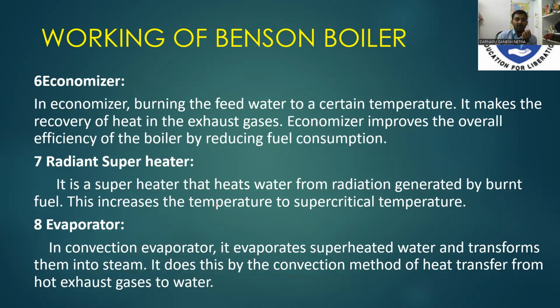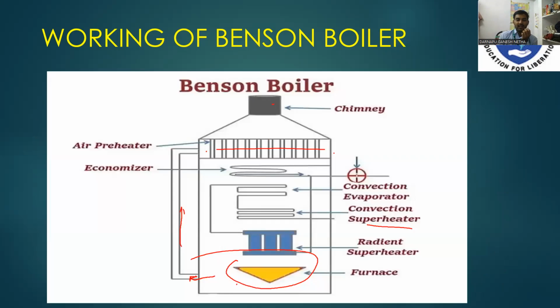Economizer. An economizer heats the feed water to a certain temperature, making use of the recovery of heat in the exhaust gases. The economizer improves the overall efficiency of the boiler by reducing fuel consumption. It is an economizer.